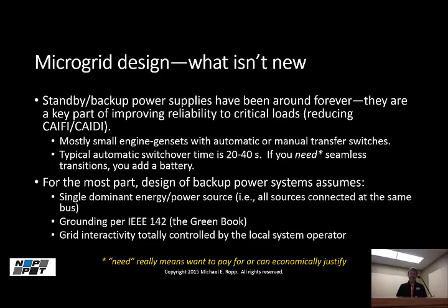If you need a seamless, or what people tend to call a blinkless transition, then you'll put a battery in there that basically acts as a UPS to ride through the period between having a grid there and having your engine genset up and running. You notice I define need on this slide. Very few customers actually truly do need blinkless power. There are some who do, right? 911 call centers and things like that. But having to reset the blinking clock is probably not going to justify the cost of a UPS. So a lot of customers really can tolerate a short blackout.